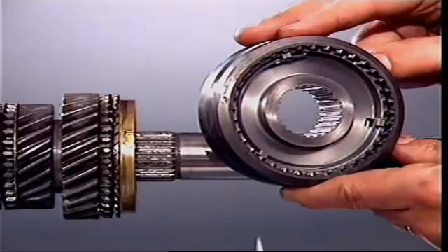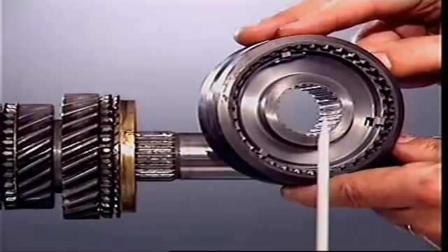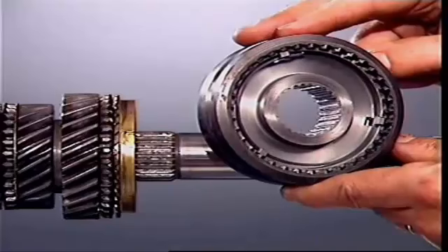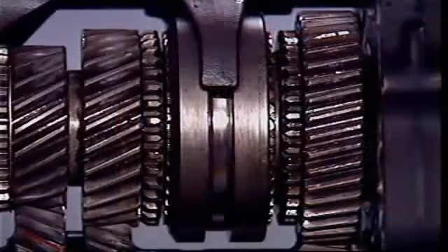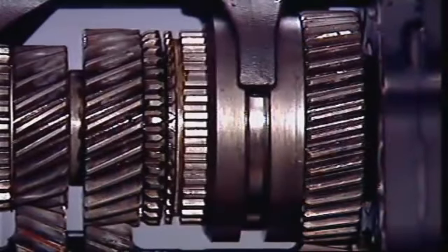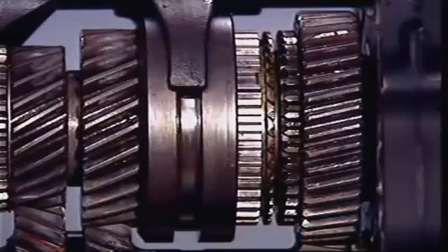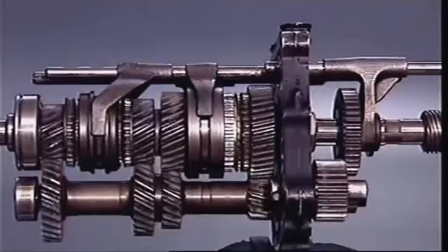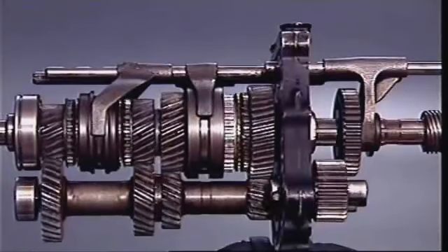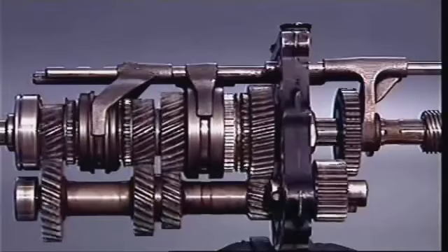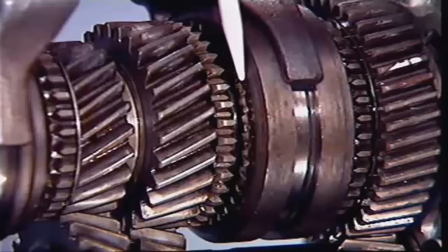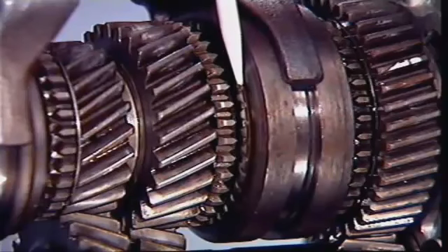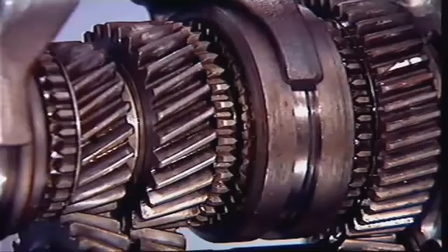The teeth face an internally toothed engagement sleeve located on a central hub, which is itself splined to the main shaft. The engagement sleeve can slide in either direction to engage the external teeth on the appropriate gear. This locks the gear through the sleeve and hub to the main shaft. Before engagement of the components occurs, a synchromesh device between the sleeve and gear synchronizes them.